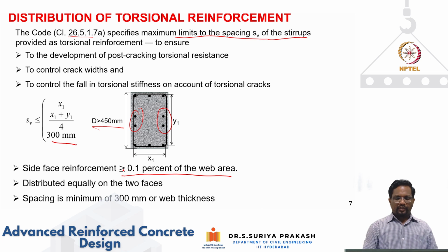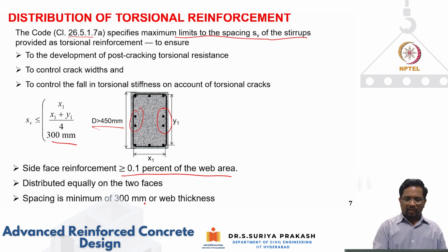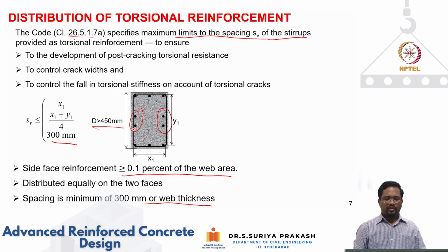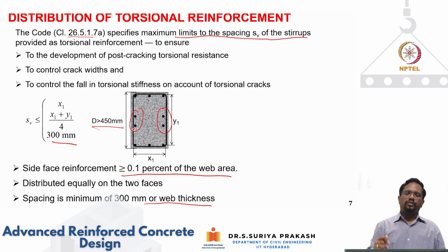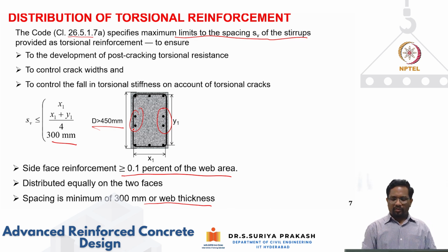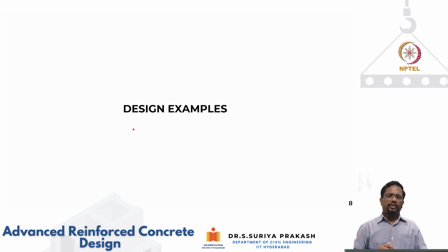Okay, and spacing is minimum of 300 mm or web thickness. So the spacing between this reinforcement also should be limited to either a minimum of 300 mm or whatever may be the web thickness. Okay, now let's see the design examples.